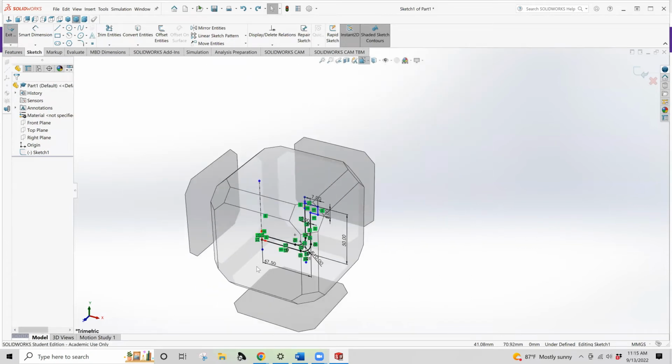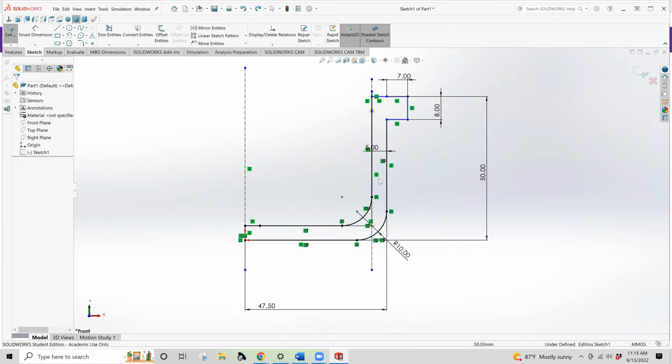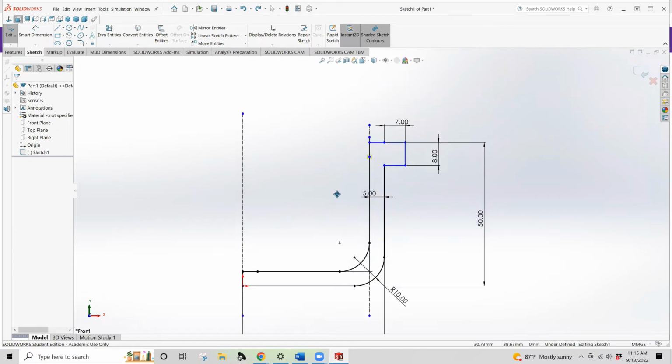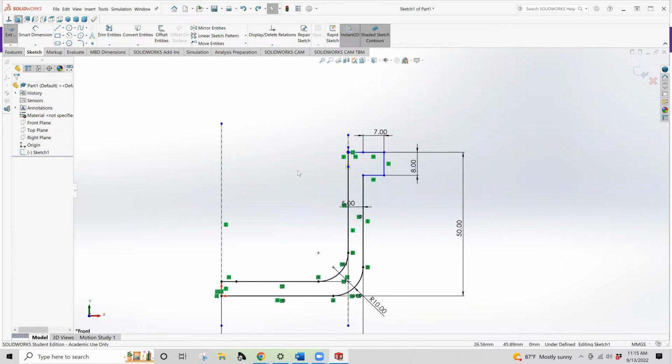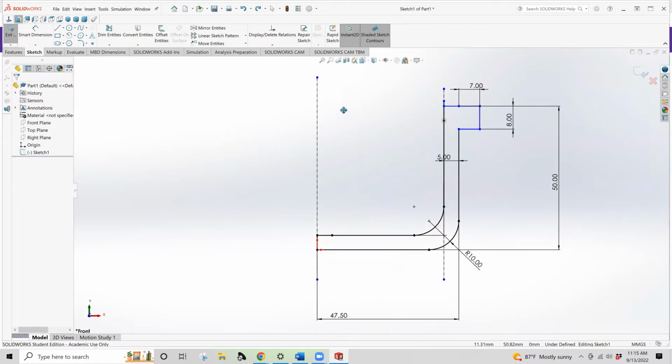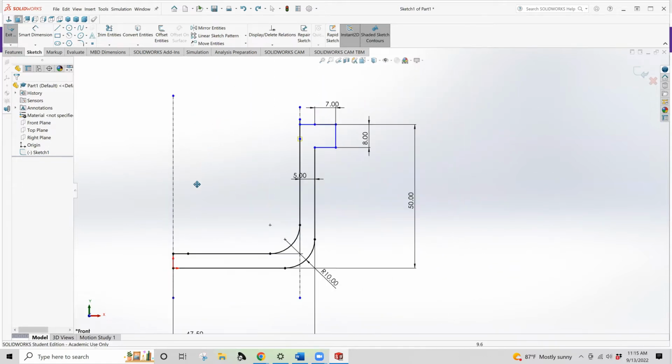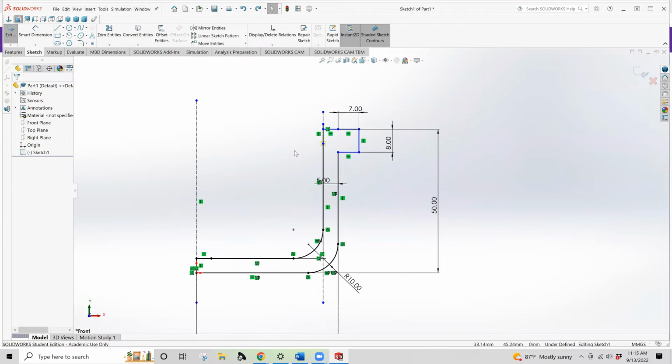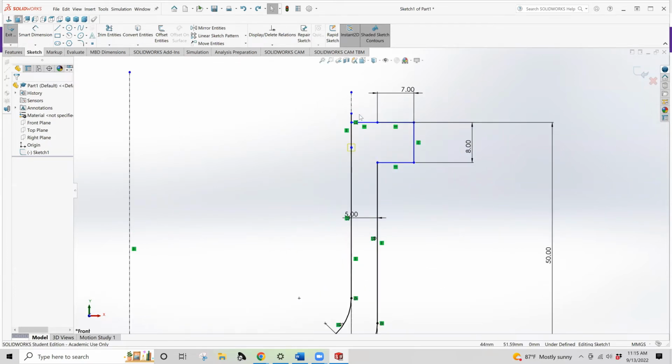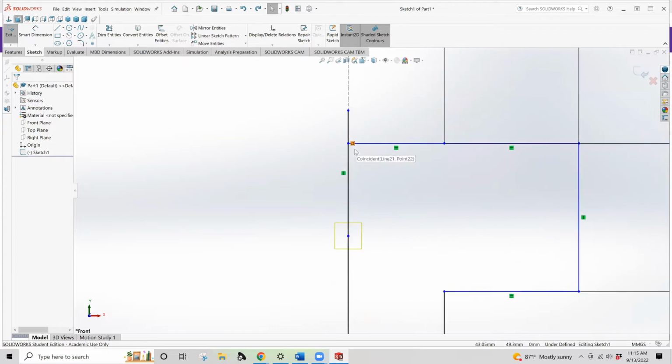Again, get in the habit of resetting your view so that your orientation relative to the part is correct. Another cool trick on sketches: you need a scroll wheel to do it really effectively, but you can hold the control key and the scroll wheel and move your frame of reference around. So you'll see me doing a bunch of stuff like that. If you're confused on, wait, how did he do that? Ask questions, because otherwise I don't know that you're missing information.